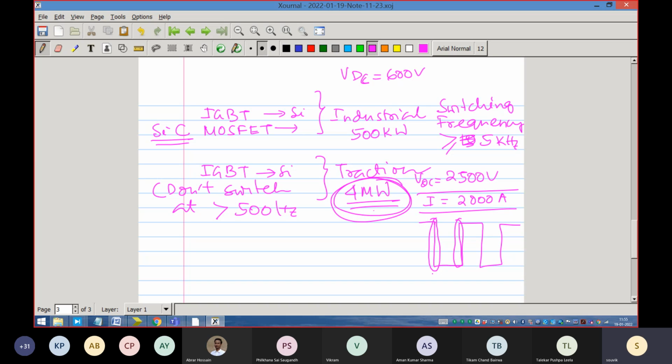For a small time duration it appears, and in these devices, because of the semiconductor physics limitation, this time is not so small. It becomes microseconds, whereas in low voltage devices, it goes into some nanoseconds. So there is also a difference. These sorts of differences produce a situation where the device's switching frequency has to be limited.